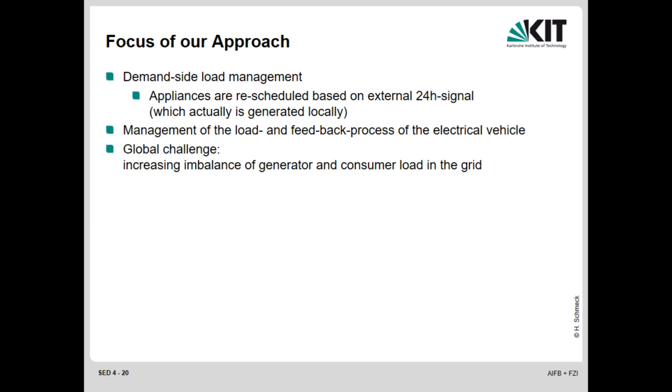So what we wanted to test there is demand-side load management, rescheduling the appliances on external 24-hour signals. Now we don't have external 24-hour signals like time-varying tariffs, but we certainly could generate those time-varying prices locally based on current market developments, which actually was done in the house.